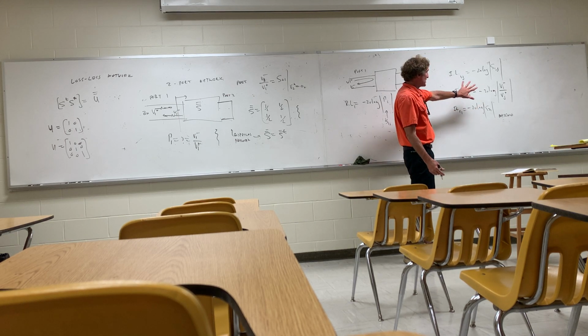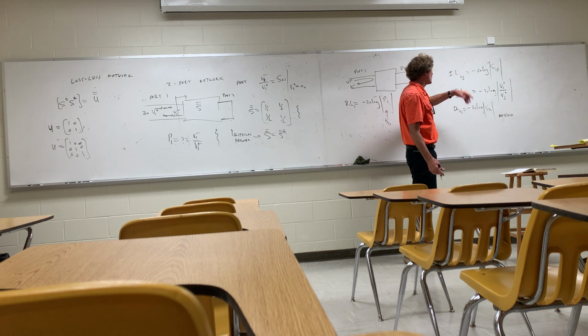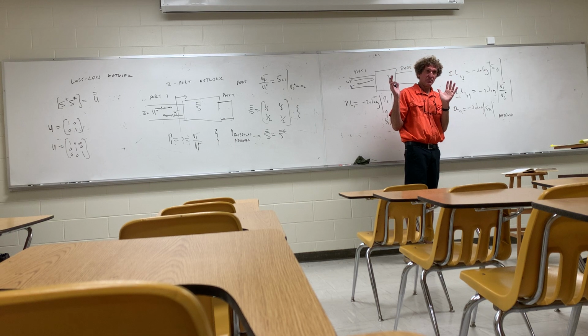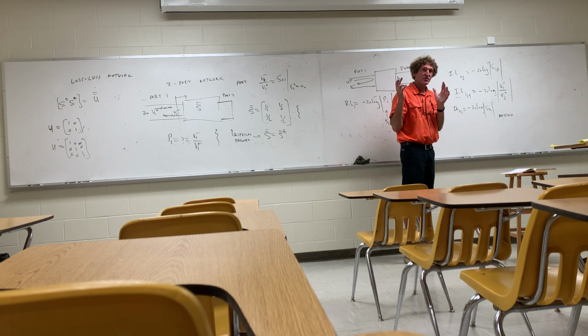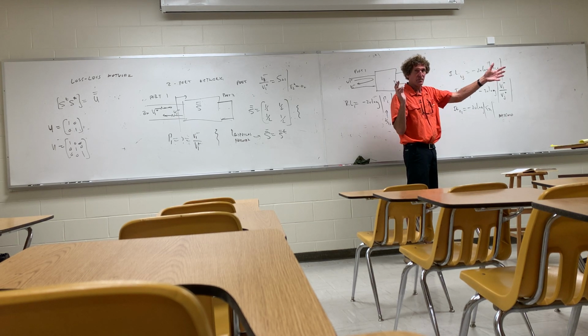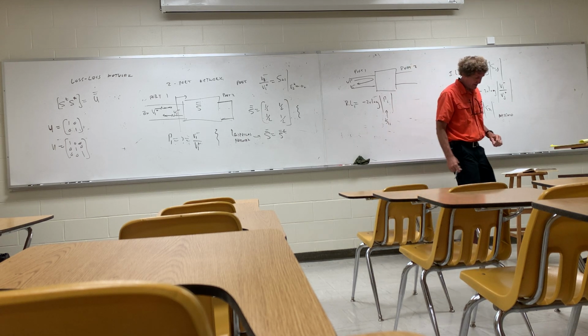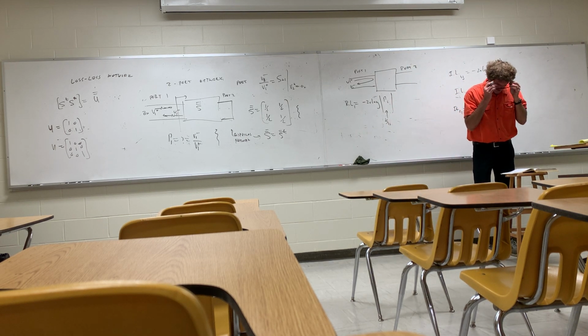Now, I don't worry that much about these two. This is pretty straightforward. If you want a loss, it's always minus 20 times the log of the magnitude of that S parameter, generally speaking. Return loss is always reflection. Insertion is always the gain. Always worry about the gain. Y'all follow me, class? And don't make a big deal about that. It's not worth it. All right.